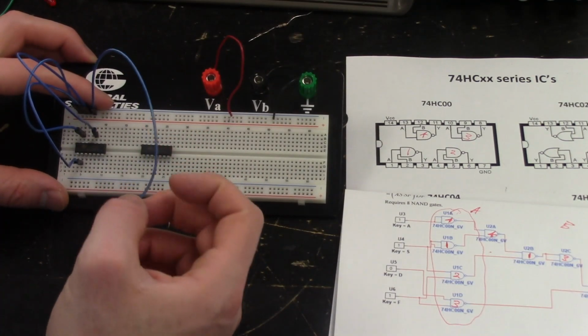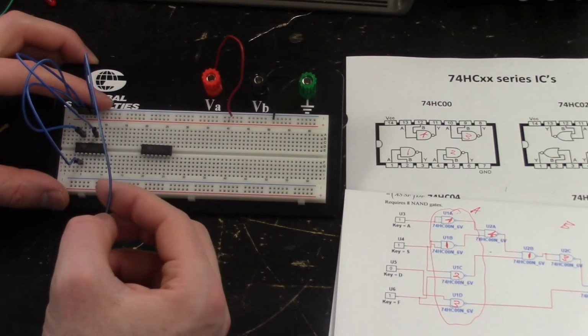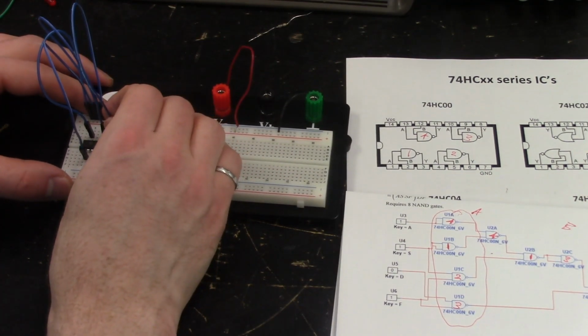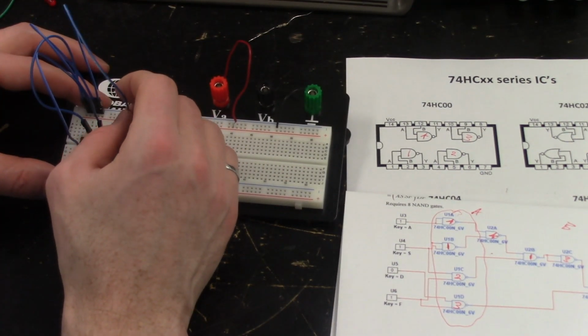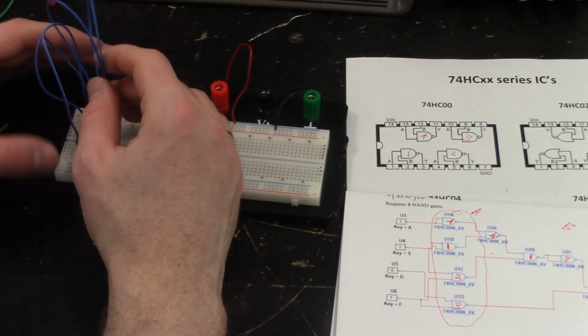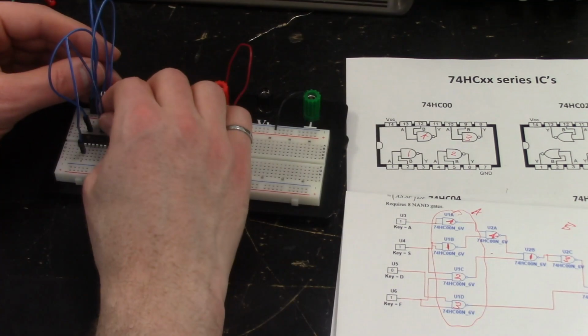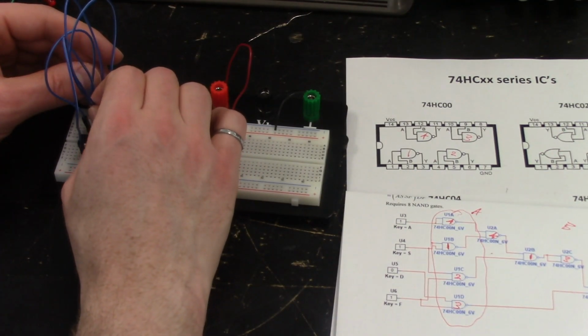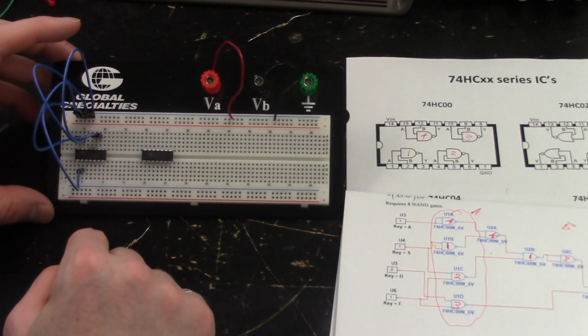So we'll take F to the input of gate number... what would be closer? Let's say the input of gate number 3, so the other input of gate 3, and that would be this one right here, beside where D is. Then we'll have a jumper wire to connect that over to the other spot that we need.